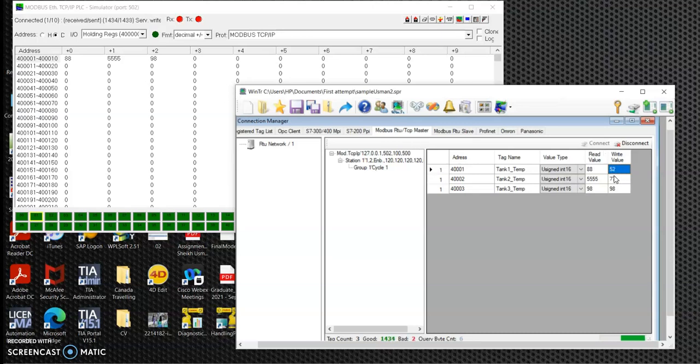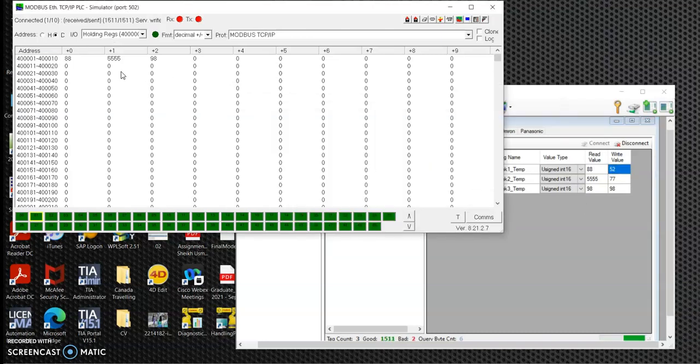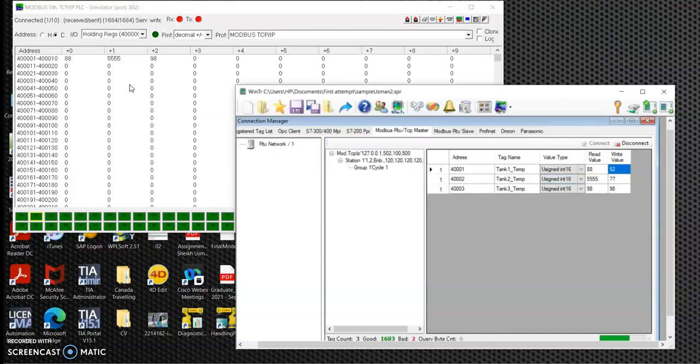So if you want to open a valve by 15%, you'll just write the value of 15 over here. It's going to pass to this simulator or the PLC, which will eventually go to the ladder logic of the PLC, and over there something would be written in the code on how to manipulate those 15% into the 4 to 20 milliamps so that the valve should open to 15% in the actual field, right? So yeah, this is how the demonstration is.